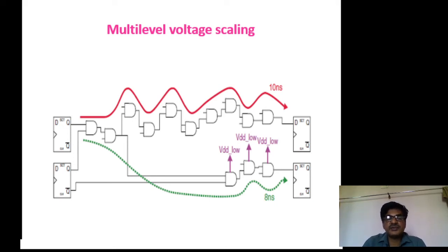Welcome back. Today I would like to discuss another type of voltage scaling technique, that is multi-level voltage scaling. In the multi-level voltage scaling technique, as you know already, it uses more than one power supply, but the selection of the power supply depends on the amount of delay provided by the subsystem.